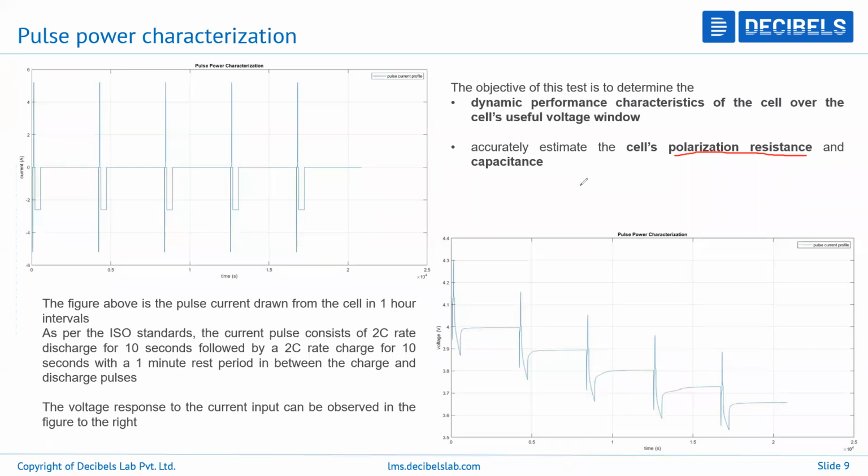As and when the cell is discharged, the voltage is not one single reading, it keeps changing, right? So at each voltage interval, what would be its possible performance characteristics, and it will also help us determine the power fade that occurs over extended usage. So it's all about performance. This is purely a test done to understand the complete performance and the performance band of the cell.